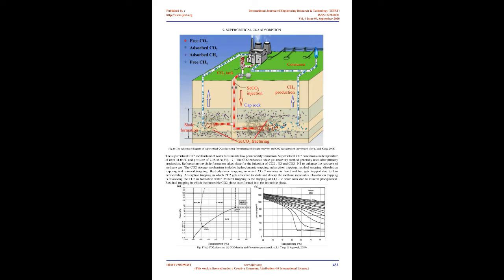Swelling/shrinkage. Shale swelling is an important prospect to understand CO2 injection for methane gas recovery. Gas sorption capacity affects gas storage, matrix swelling and gas flow mechanisms in nanoporous organic-rich shale gas reservoirs, Pang, Chen, Solomon, Morse, and Hu, 2019. In published literature, three kinds of shrinkage are available: transient shrinkage, slow swelling, and stable strain. Swelling occurs when CO2 gets adsorbed on the surface of shale and tends to increase the size of pores, reducing surface potential energy of shale. This response will result in a closing of fractures and reduction in permeability of formation.